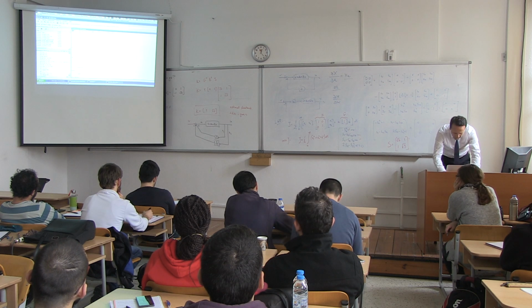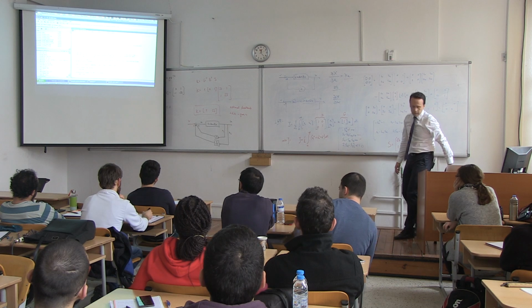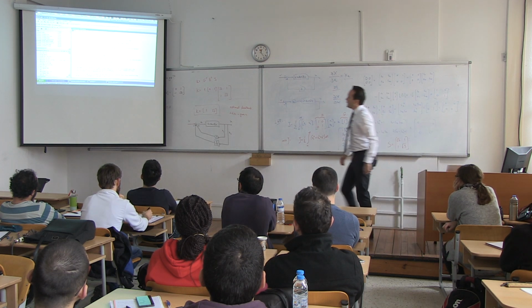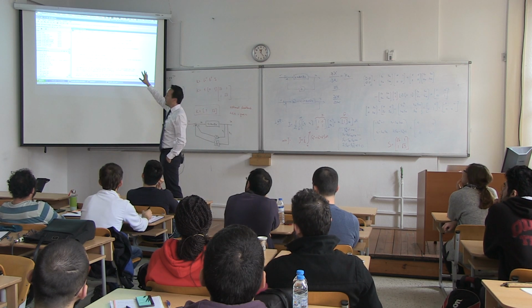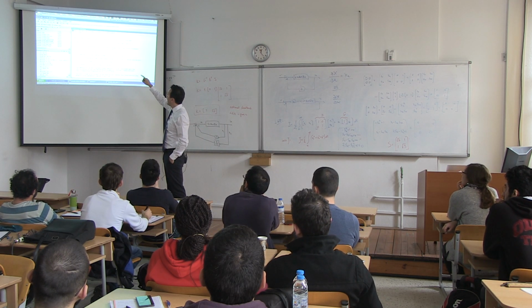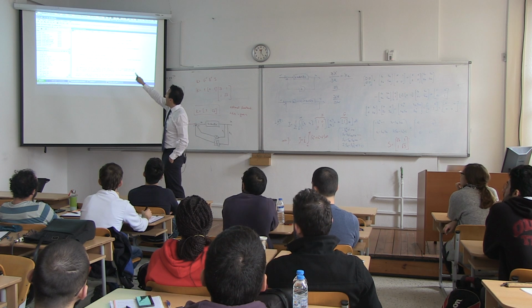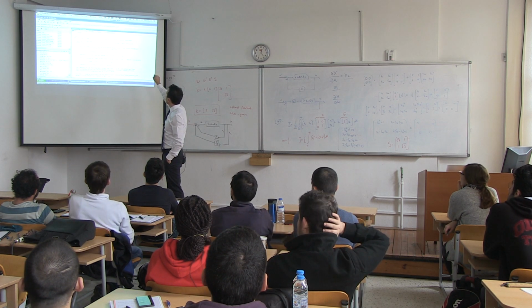So, help LQR. Boom. I really apologize, you can't really see this very well. So LQR is the command. I just wrote help LQR, that's the command. LQR, linear quadratic regulator designed for state space systems. That's what we have. Okay? K, S, and E, LQR, system, Q and R, and all that stuff.